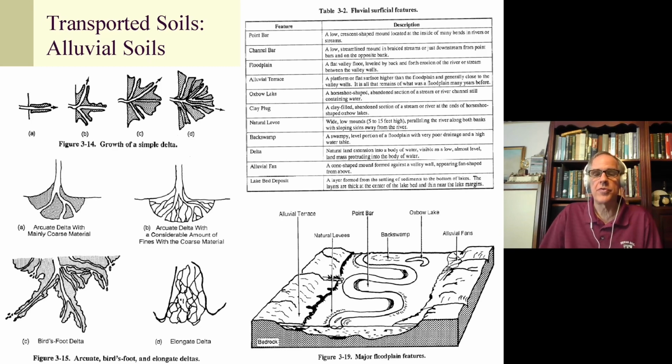Because the Corps, for flood control purposes, and because the Corps was trying to avoid the Mississippi River changing course from the Mississippi River to the Atchafalaya River between Lafayette and Baton Rouge, the Corps developed a system of channels and whatnot that basically channelized the flow of all of the sediment, the alluvial sediment. So therefore, not only did the delta stop growing, it actually retreated. And actually, Louisiana has been shrinking for a long time.